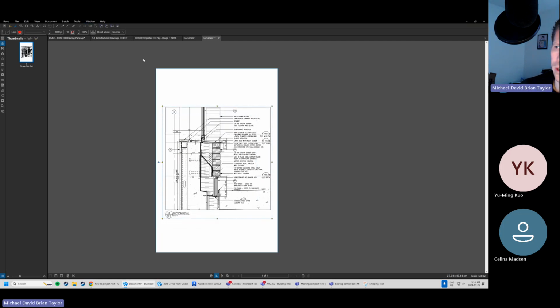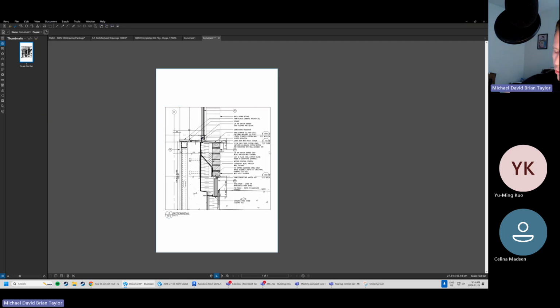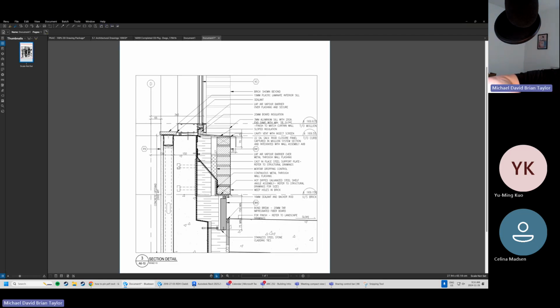First thing I'm going to do inside of Bluebeam, this is just a personal preference, is that I am actually going to flatten this drawing. So once I flatten it, it's going to make it impossible for me to move this element here. And that's it. This is really step one. I've just got one detail, one sheet, high fidelity PDF, and we can see all the detail from this detail. You know, the details that you use don't have to have this much detail, but it is helpful as a starting point. How would I get this information into Autodesk Revit?